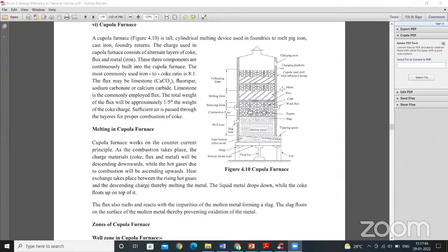That is why furnace manufacturers are now moving from a 6 pulse converter to a 12 pulse converter. If you go for a 12 pulse converter, automatically the harmonic level gets reduced, and it will also improve the efficiency by at least 10%. That is, 10% energy saving is possible. The only thing is the initial cost is going to be higher, but it can be recovered within 3 to 4 years, because you have fewer harmonic problems, and a minimum 10% energy saving is possible because of the higher pulse rating system. Quickly it will heat up.